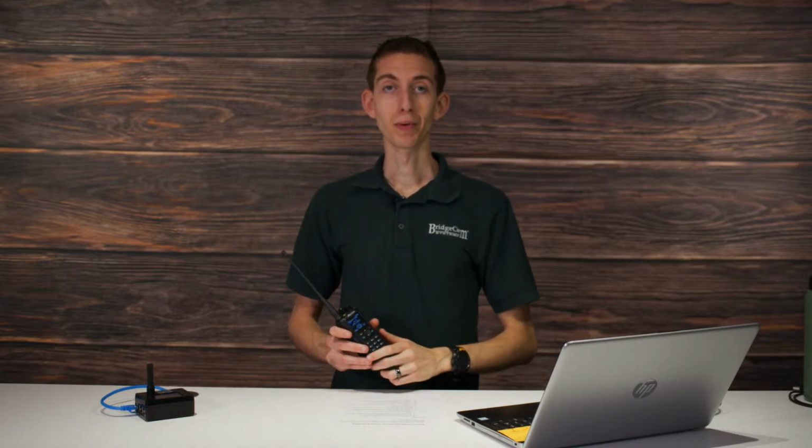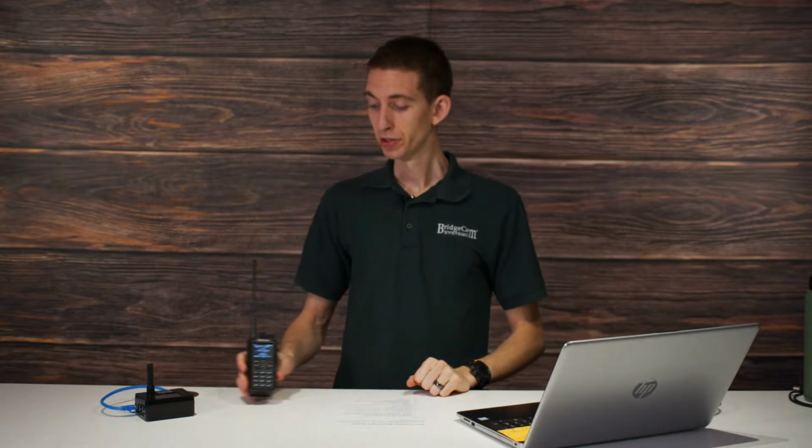Now, the easiest way to remember what your transmit and receive frequencies are is with this uplink and downlink system. So in this case, uplink, in the eyes of the radio, radios are going to be down low on the ground, right? So you have your people on the ground with the radios. That's how I like to think of it. And repeater systems are going to be on a tower up in the air. So they're going to be up high. So uplink, if you're talking about the radio, what you're programming in here, uplink's going to be your transmit, because you're transmitting up to that repeater. Or in the case of the other, downlink, that's going to be coming down from the repeater. So just keep that in mind.